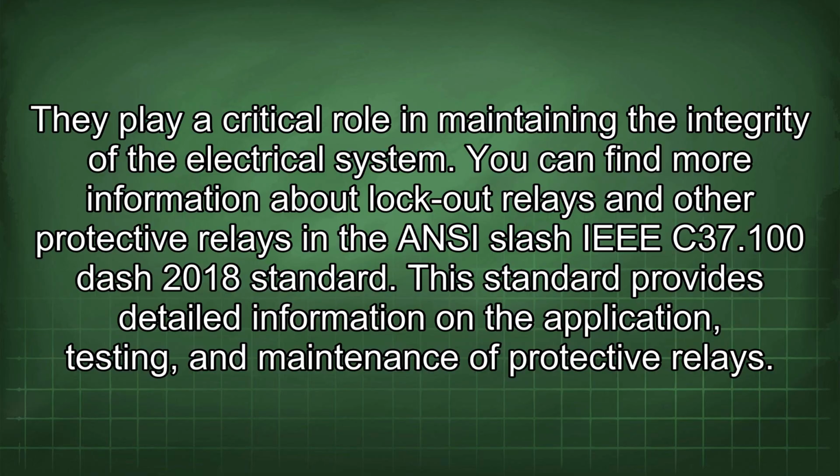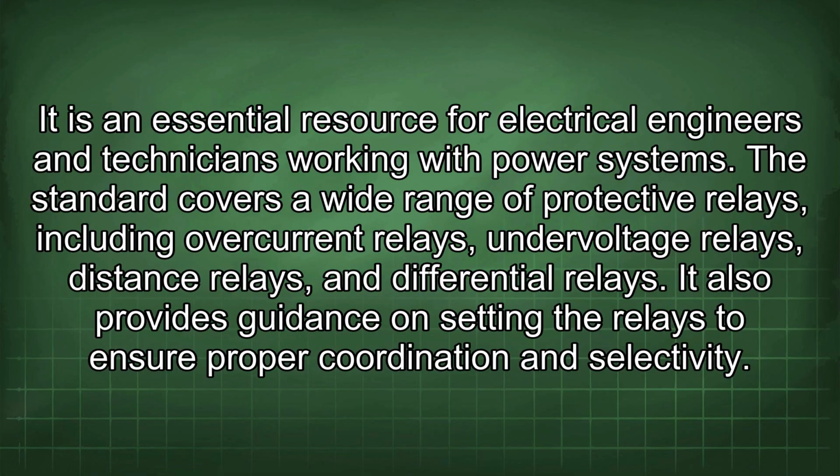You can find more information about lockout relays and other protective relays in the ANSI/IEEE C37.100-2018 standard. This standard provides detailed information on the application, testing, and maintenance of protective relays. It is an essential resource for electrical engineers and technicians working with power systems. The standard covers a wide range of protective relays, including overcurrent relays, undervoltage relays, distance relays, and differential relays. It also provides guidance on setting the relays to ensure proper coordination and selectivity.